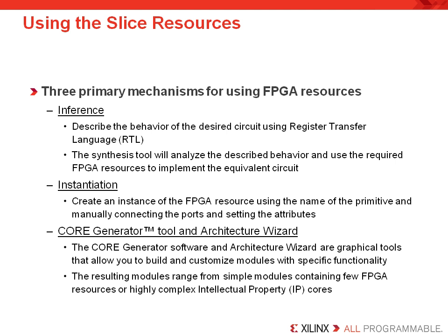First of all, one of the best ways to check that you're getting the best resources is to use your synthesis tool's schematic viewer. All of the high-end synthesis tools have schematic viewers. Viewers are used to graphically display a gate-level version of your netlist and also a technology view of your netlist. While a gate-level netlist is worthwhile to check the Boolean optimization produced by your synthesis tool, the technology viewer helps you understand what Xilinx primitives were inferred, or more importantly, what primitives were not inferred by your synthesis tool.